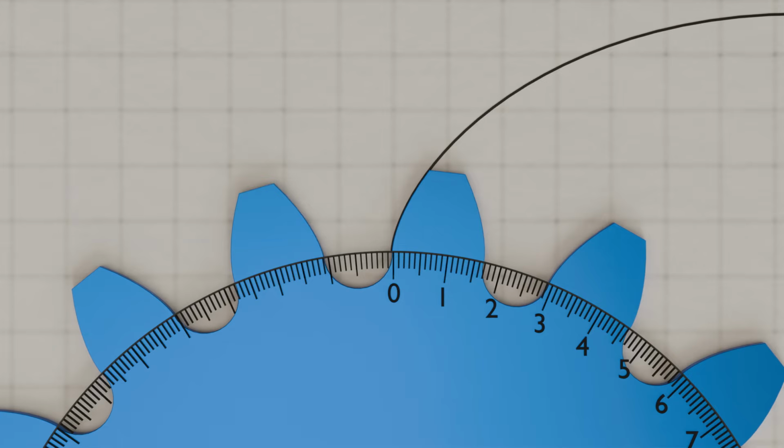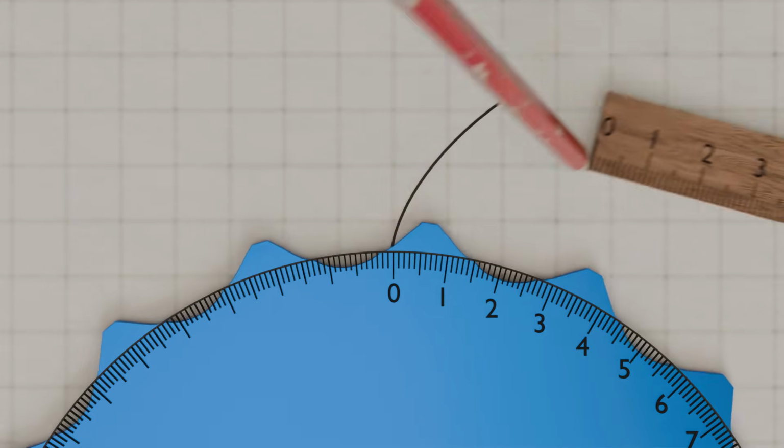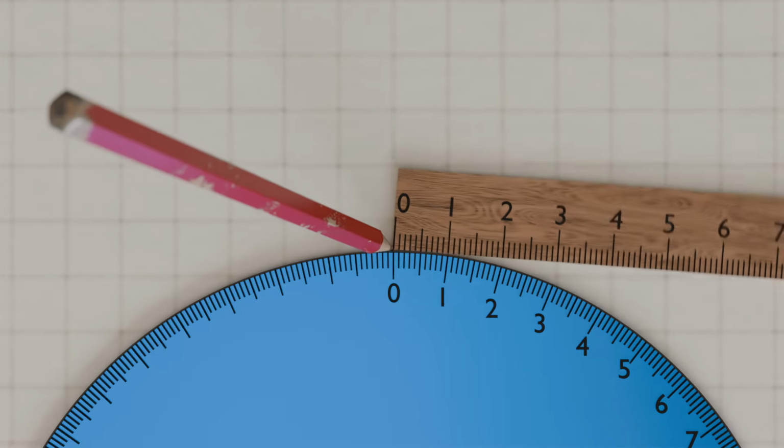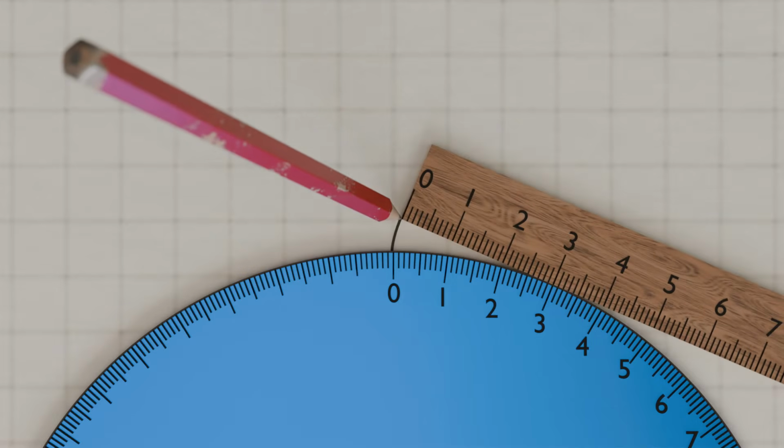If the involute is constructed with a rolling straight line, it becomes particularly clear that the longer the involute, the less it is curved. In this case, the radius of curvature of the involute is 3 centimeters. The radius of curvature is the distance between the point of interest on the involute and the point where the straight line touches the base circle. In principle, this is the same as the arc length on the base circle, since the straight line is rolled on the base circle without sliding. This fact will become relevant later with the so-called base pitch or meshing pitch.